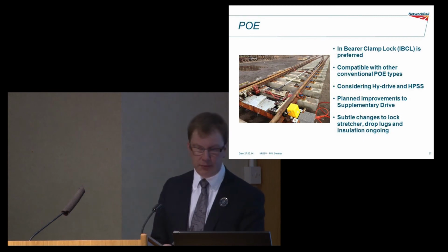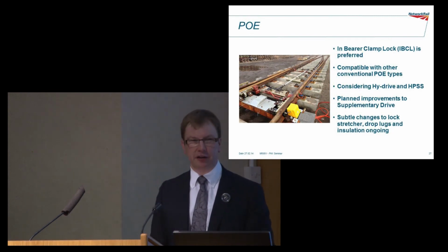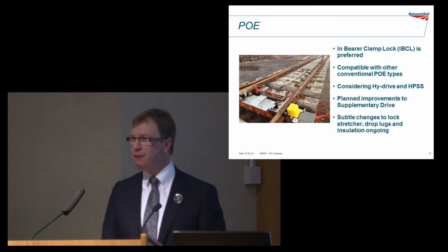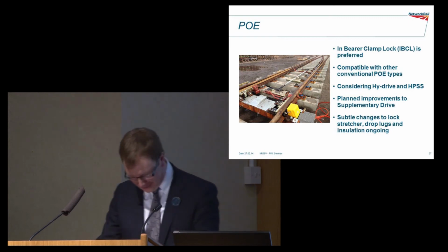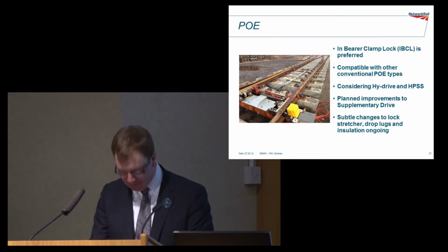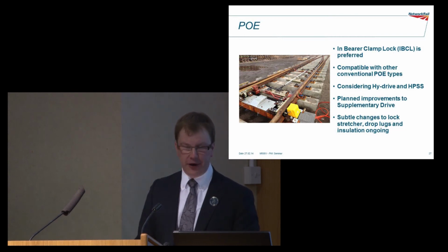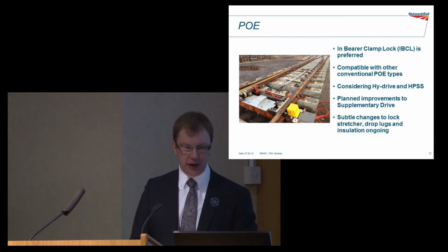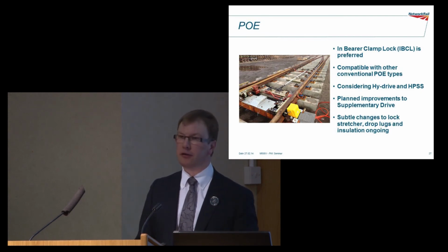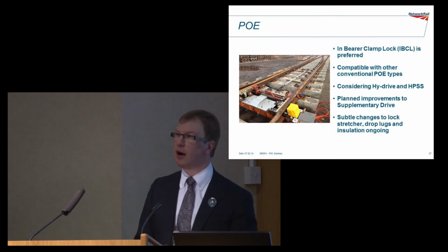Points operating equipment, POE. If we've got a room full of signal engineers, we get hisses and boos. Whichever method of POE we talk about, we get a real passion. Some love it, some hate it. Maybe we get it amongst track engineers as well. But in-bearer clamp lock is the preferred POE system for NR56V, but we have got the holes in the rails for conventional POE types as well.